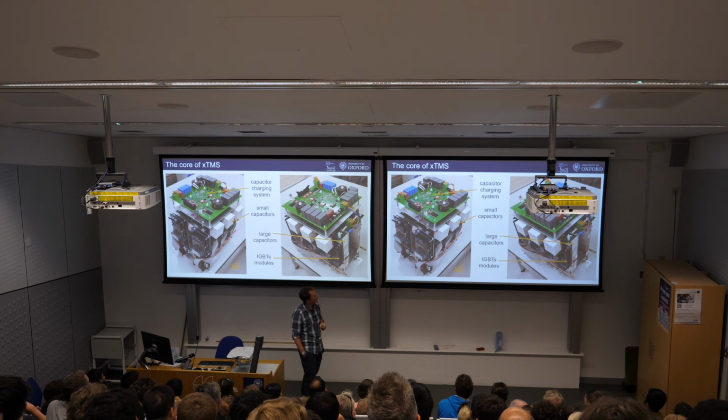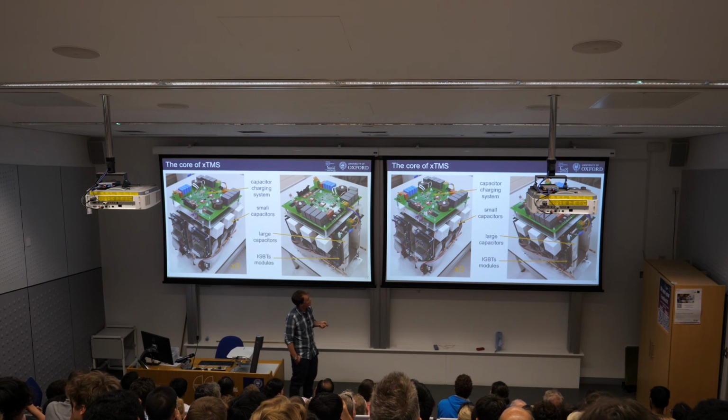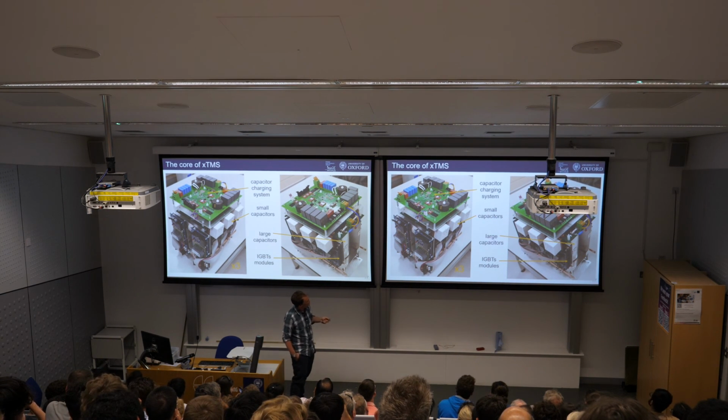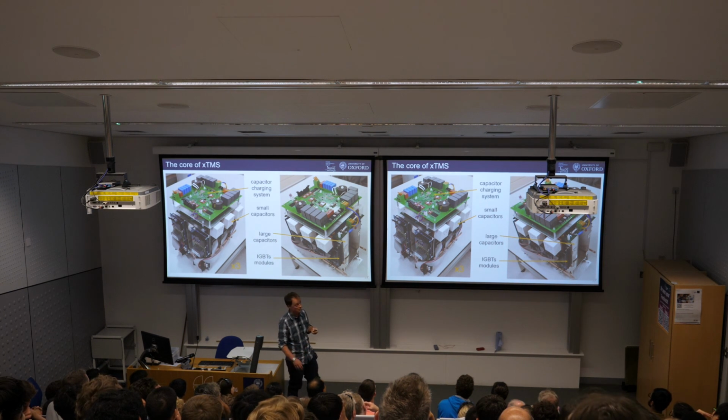Oh, bit of zoom in. So this is sort of the core power module. There are 3 of these in the system. You can see it's relatively complicated. You can see the large energy storage capacitors just hidden here. These are large power transistors, all connected together with large copper bus bars to carry this very high peak current.